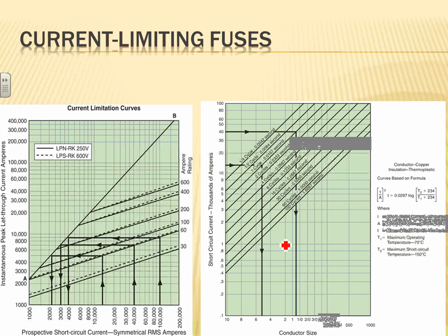The fault current itself is calculated assuming there is no overcurrent protection device in the system. It's only the impedance. But the arc flash will take this into consideration. When you do your arc flash studies and the labels, I believe it will take this into consideration. But the short circuit would not. So we'll get into that one. Here's a couple of examples, guys, of current limiting fuses.